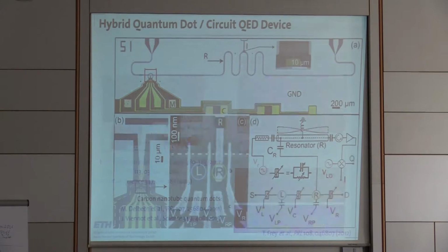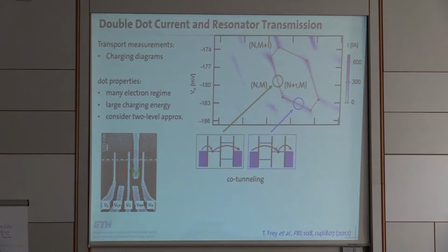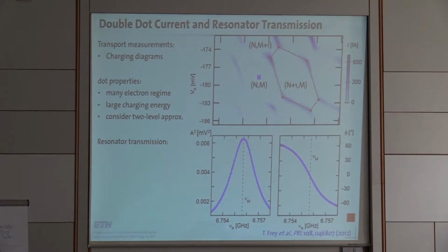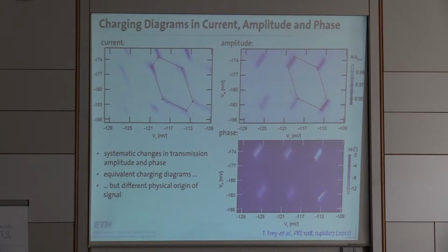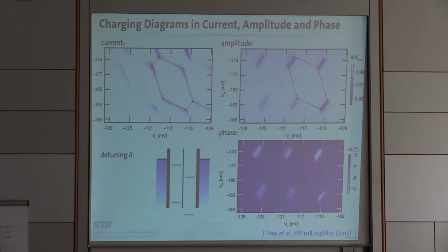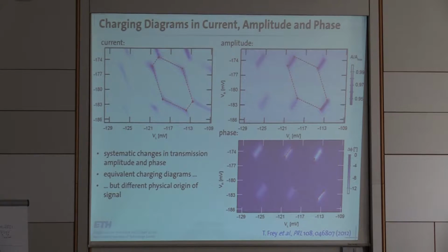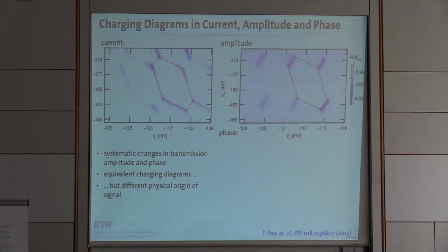Okay. And I guess you're worried because you could think that it could charge up and do something weird to your quantum dot and would not be a controlled gate voltage on your quantum dot. If it was floating, we would have to see a difference from the number of electrons charging the quantum dot in principle. But you don't see this. That's why I had this question.